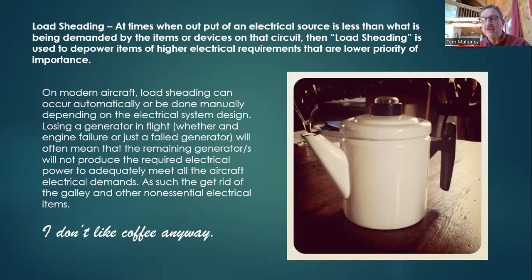Now, in flight, I can use electrical power quite a ways, pretty high in altitude, unlike pneumatic power. Electrical power, I think, on this aircraft goes all the way up to the service ceiling of the aircraft. So I'd start that APU, and then I could go ahead and turn that galley power back on so the flight attendant could continue to serve those passengers their coffee, or at least the other pilot who drinks coffee. All right, that's what load shedding is.